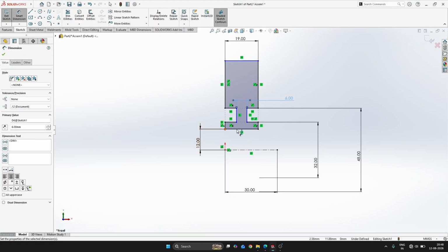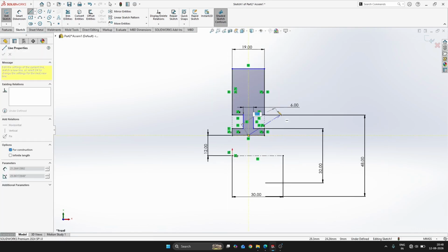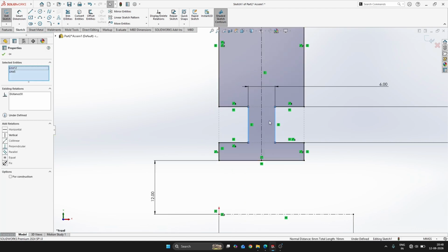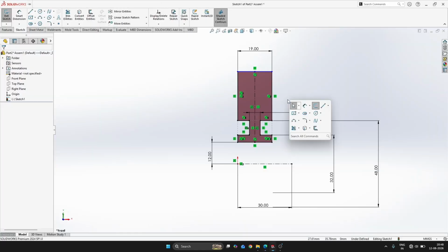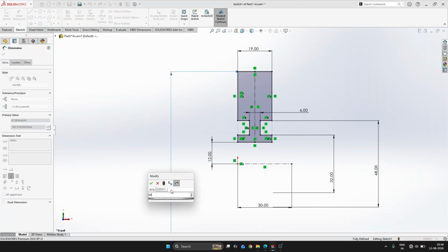Okay, and this has to be center. How can we make it? So click on line command again, but center line, make it like this, and these two lines, make them symmetrical about the midline. That's it, they are constrained. Now what is a OD? So which is 64. Set up this and this, so 64.